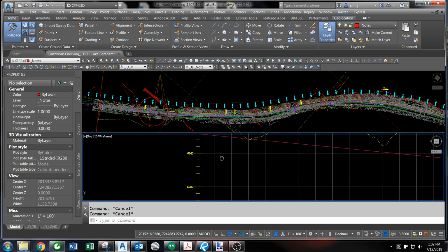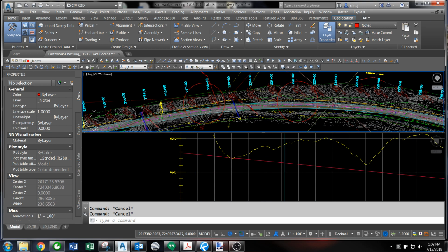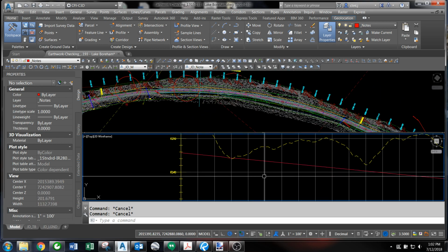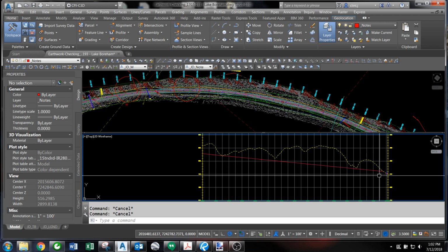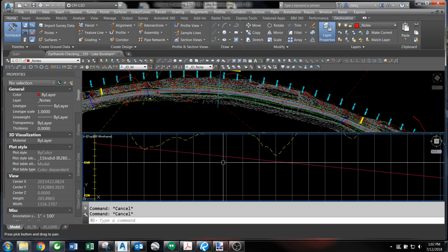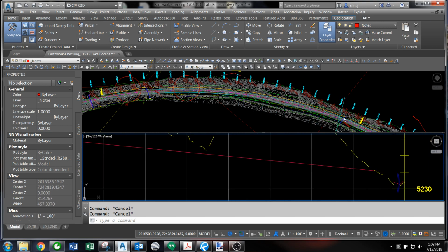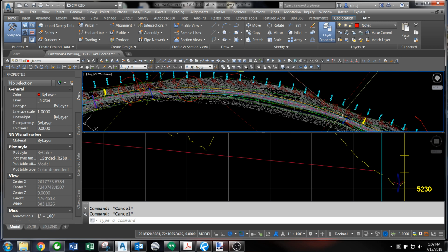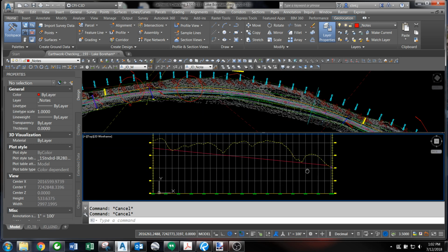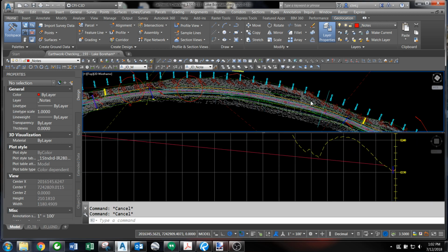Some of the ditches didn't need anything. This is one right here. You come up here to this cut here. It's one I looked at. I ran my ditch line and I looked, and we got water that's going to flow down on this red line, and then it's going to daylight out and it's going to hit that culvert. Perfect. I didn't have to do anything there. I didn't have to do any manual control or override of the ditch there. I was happy with what it was doing.